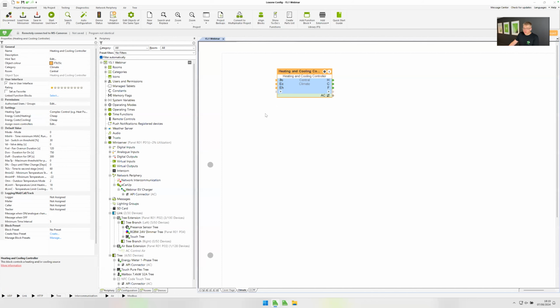What we can now do is touch over a couple of additions to the climate controller, or now the heating and cooling controller. Previously, you could use the outdoor temperature to influence whether we're restricting to only heating or only cooling, or maybe you can do both, based on the average outdoor temperature over the last 48 hours, otherwise known as weather compensation.